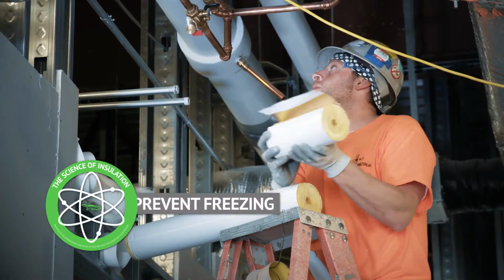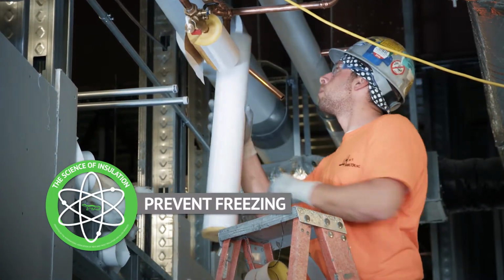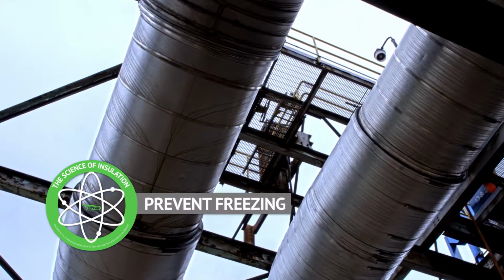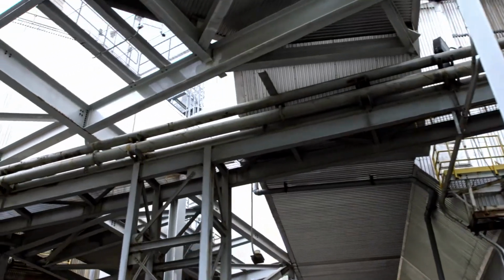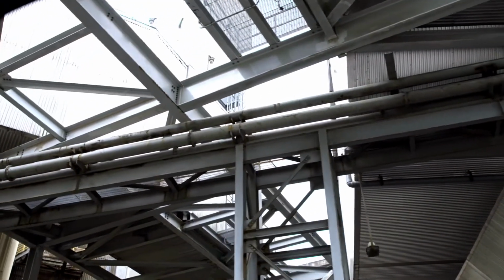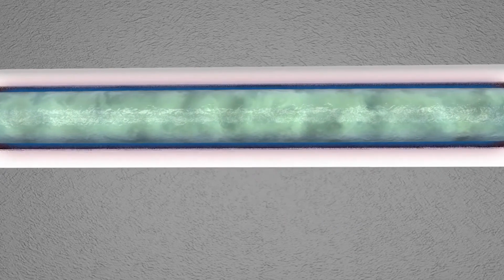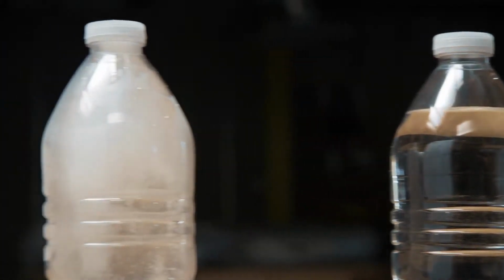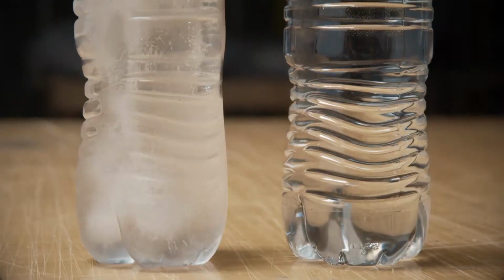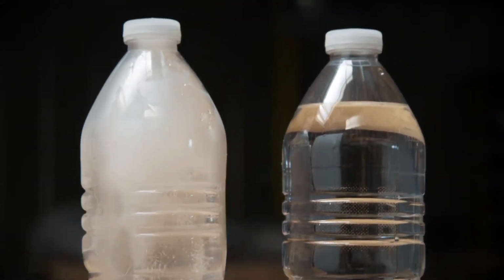Another main reason for insulating is to stop something from freezing. While it's important to maintain the ideal temperature of the contents in a heating or cooling system, it is important to not let the temperature become an extreme. If we were insulating a pipe that was carrying water and the temperature got below 32 degrees, the water would freeze. Water has the properties of many other materials and expands when it freezes. When the contents expand, the pipes are stretched. This could result in pipes bursting because of the material expansion.